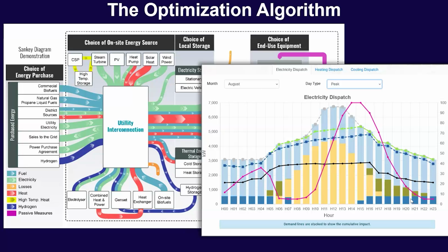And this now creates this benefit that we're charging some of the battery here in the morning, so that we have it before the sun comes up. This is because we are utilizing the CHP system at high efficiency. Then, of course, we use some energy from the battery in the morning. And when the PV is operational, we recharge the battery again. So this is a combination of charging from a PV system and a CHP system.